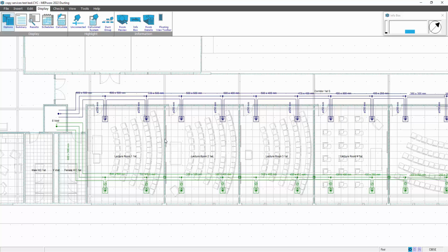So if you imagine you're looking at the heating as your basis of your calculations on the ground floor, and you have a ground floor exposed floor plate, if you're copying that upstairs, obviously there's going to be a modicum of oversizing because the losses upstairs will be slightly less because you only have an external wall. So there are checks and balances in place. Likewise with cooling, if the basis was cooling and you travel up through the building, the lower spaces may be in shade, upper spaces may not be. So there may be a modicum of undersizing. So we have checks and balances in place.